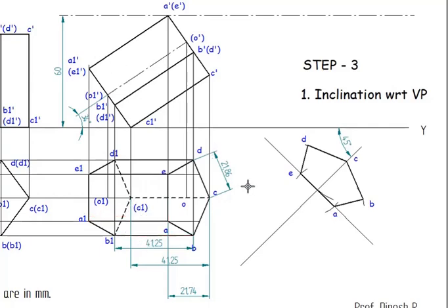So now I'm going to draw a line from this. Take the roller scale, draw the line parallel to that, which is equal to 45 degrees. I'm going to draw a line. I'll take an arc by center point. From this point I'll cut 41.25, drawing an arc.